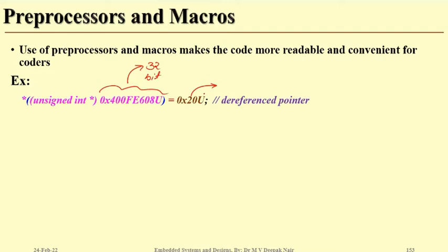Now we are entering 20. What does that mean? To enter a 32-bit value, you should enter something like this, 0x00000020. This is the value we should enter, whereas we are entering just 20. What does that specify here? All the zeros preceding this 20 are ignored, so it does not matter. So at the end you are going to enter 20.